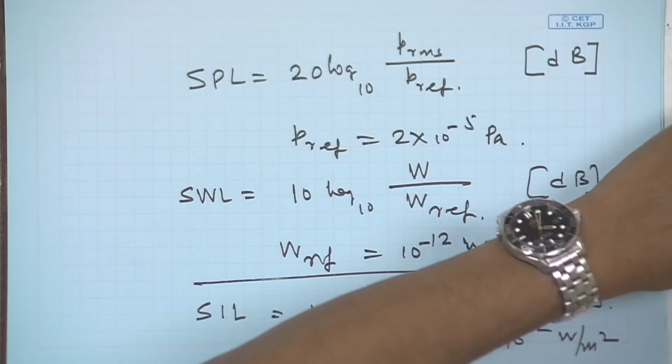Okay. And you all know how to measure SWL of a product. You can multiply the normal intensity and the corresponding area and sum them up and get SWL. Other methods of SWL are by comparison method with the reference source, measuring the SPL in a hemi-anechoic chamber, etc. Such exercises are being taken by Indian industries to label some of their products. It has not been mandated yet, but it will come, that when you buy a genset or a refrigerator, its SWL would also be stamped, and that would make everybody's life easier.